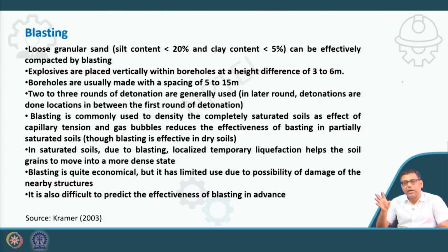So that means first we do the testing, and then we check how much densification has been done. Based on that, you go for a second round or third round. When you do the first round of detonation, you check how much densification has been done, then you go for the second round, with detonation done in between the first round locations. If required, you can go for a third round of detonation also. Okay.